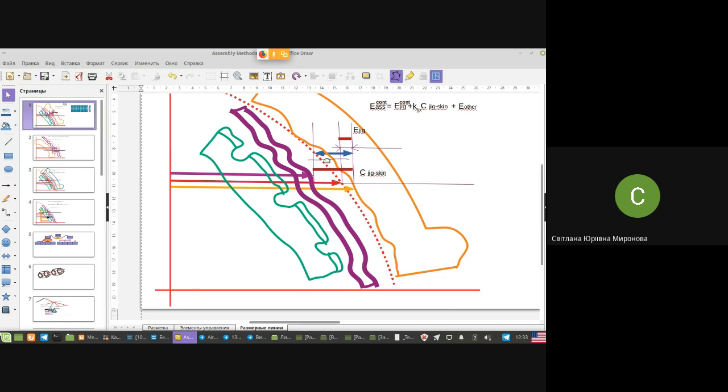That is the reason the difference appears. This difference may be reduced by applying the clamps, which will narrow this clearance between the outer surface of the skin and the outer surface of the locator. And because of this, the skin will more accurately repeat the locator. And I hope you remember that the jig is, on one hand, produced more accurately once.